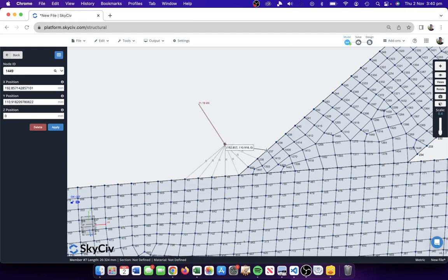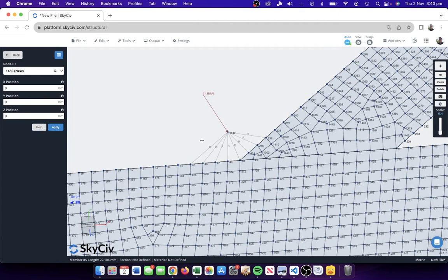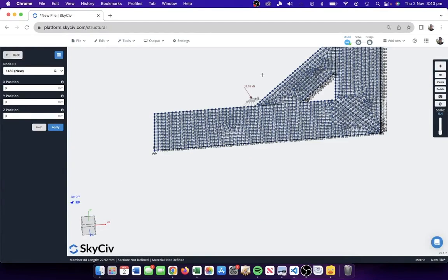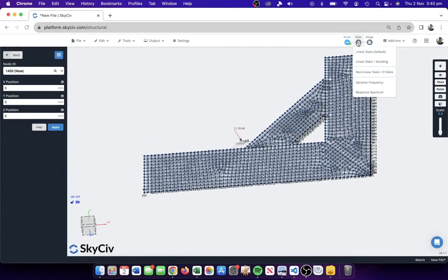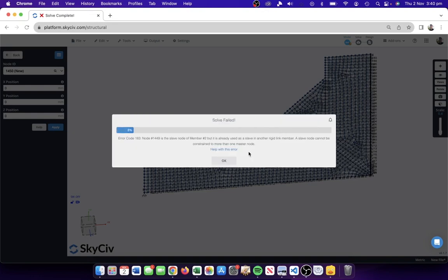Sometimes you want to look out for eccentricities, but for the moment they're quite small in this case. So this is a good way to evenly distribute a point load to a number of different nodes, and sort of see a more realistic stress profile on those particular plates.